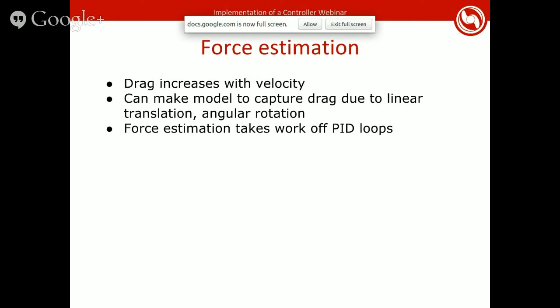You can use those studies and experiments directly in your model. A simple thing you can do if you don't have that option is to segment your vehicle into planes. The more planes you have, the more degrees of freedom you can capture. Sometimes there are forces induced in the vehicle due to the Bernoulli effect. Some parts of the sub might be smoother, and if you're swaying, and the back of your vehicle looks a little bit different than the front, there might be some heading torque induced there.